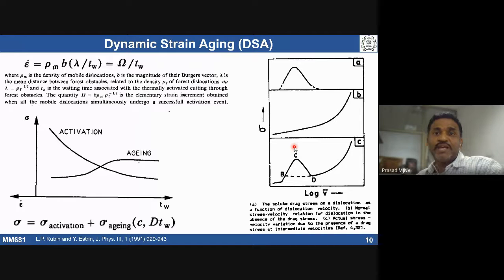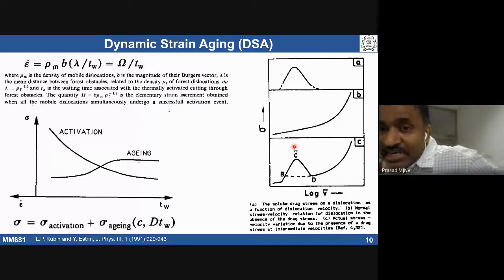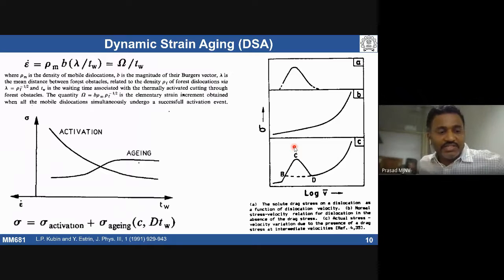This is also another plastic instability, because there should not be a sudden increase, because that basically causes a lot of problems during working of the material. Blue brittleness is one of the best examples that come under the category of dynamic strain aging phenomenon. The explanation is related to why you see a plateau or an increase in stress during the dynamic strain aging phenomenon.